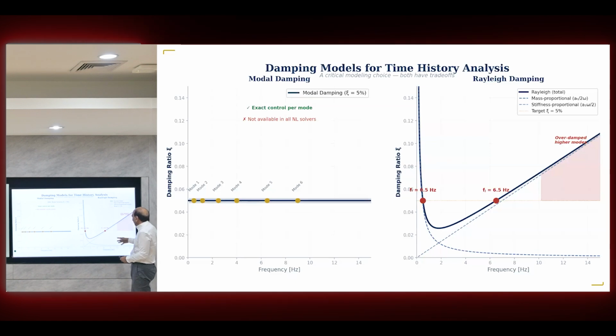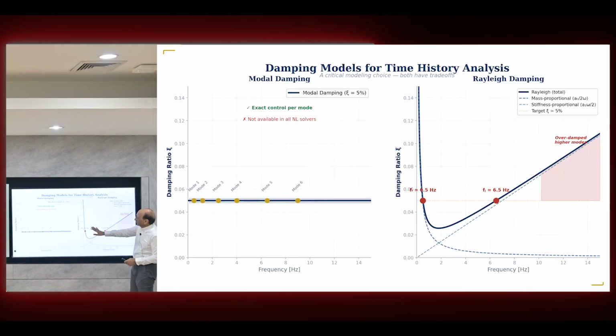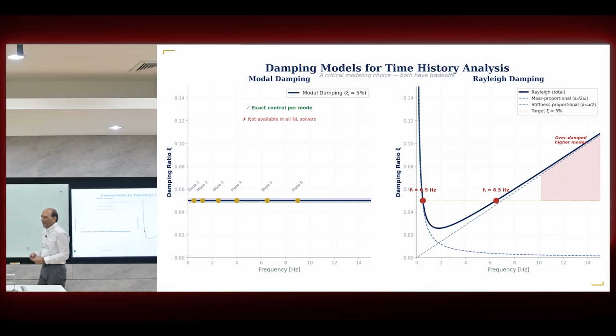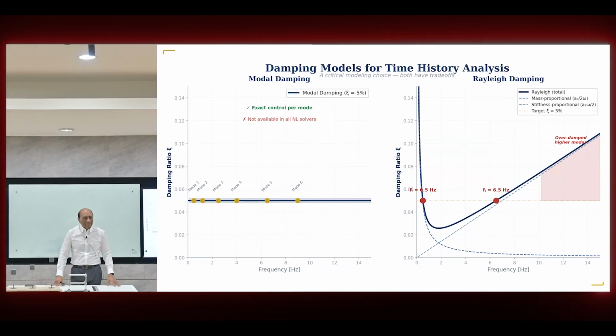effect of damping. When we look at the damping, it's an over-damped structure, and then how the damping will change. We discussed this, but damping is still very important, because we are going to talk about the response spectrum, which will depend on the modes. And of course, for the linear time history analysis, the modes will be automatically determined and included.